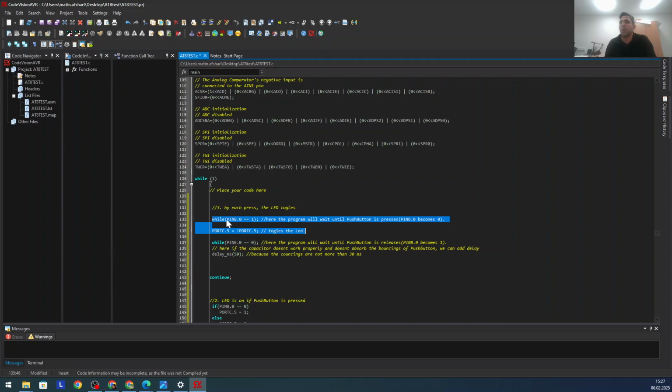In this code that we have, a few hundred lines of code, it will take maybe 200 microseconds for the entire code to run through. And so the microcontroller does this hundreds of thousands of times a second. If we have the 8 megahertz clock speed that we have in this project, it's reading this code over and over again, just repeating this cycle.